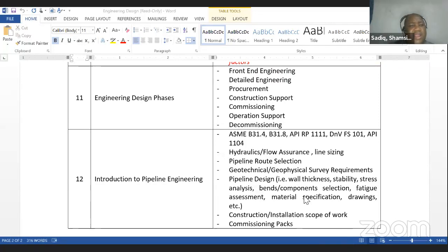Imagine in Nigeria, I think there's a mill in Abuja that can do some form of pipeline, and that type of pipeline the mill can produce is not the one you want to use for oil and gas, for high pressure operation or even typical oil and gas application. Probably they are best used for water. So you need to be able to know the industry, the mills that produce these line pipes, understand the specification, limitation of these mills, and the kind of quality you get from them.